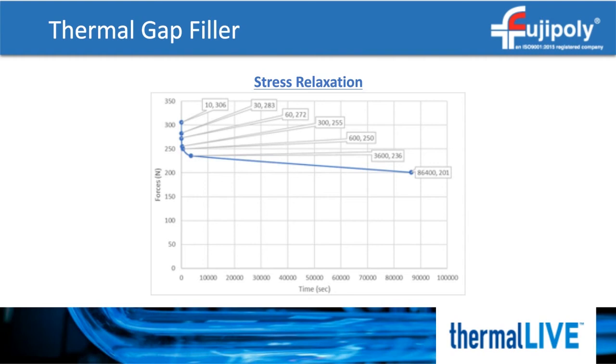Important to remember the forces are highest during the compression and generally relax once there is no longer any further deformation. Managing the compression from initial to the target percent compression is critical in ensuring the assembly does not undergo more stress that will cause damage to the PCB or solder joints.